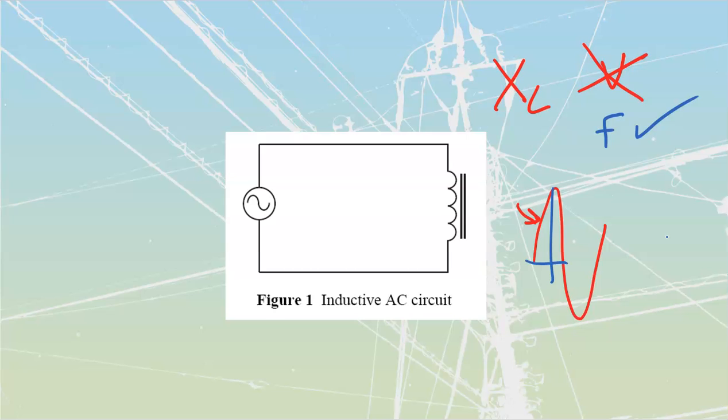If I take that L value and I double it, and I work off the same counter EMF formula, E = -L ΔI/ΔT, then if I'm going to still maintain the same value of voltage, I would have to decrease my ΔI over ΔT, right? If I double the L, halve the ΔI, that way I can maintain the same E. Which would mean that my peak current is also going to decrease. And if current has decreased, that simply means that there is more opposition to current flow, more reactance. All of this is going to make a difference inside of here. So my L and my F both are going to make a difference inside here.